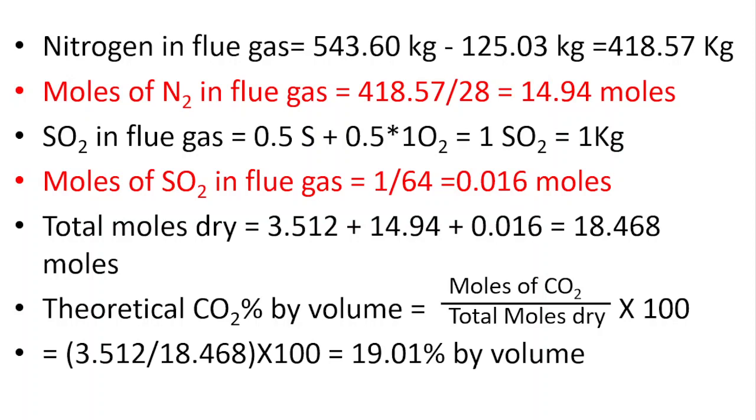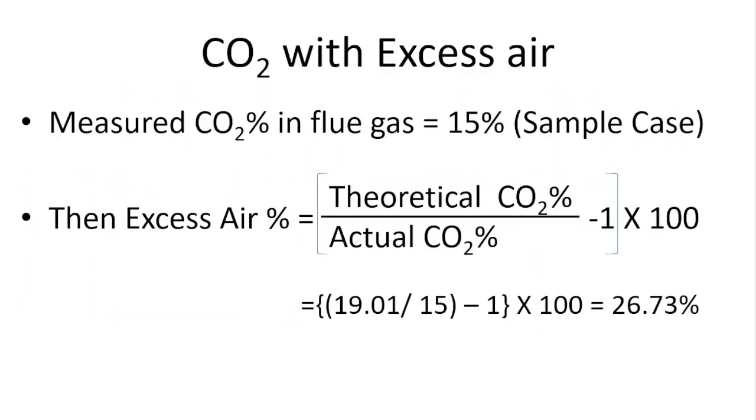So the theoretical CO2 percentage by volume is equal to moles of CO2 divided by total moles dry, times 100. So that comes out to be around 19.01% by volume. So if you measure the CO2 percentage in flue gas, theoretically you should get 19.01%.